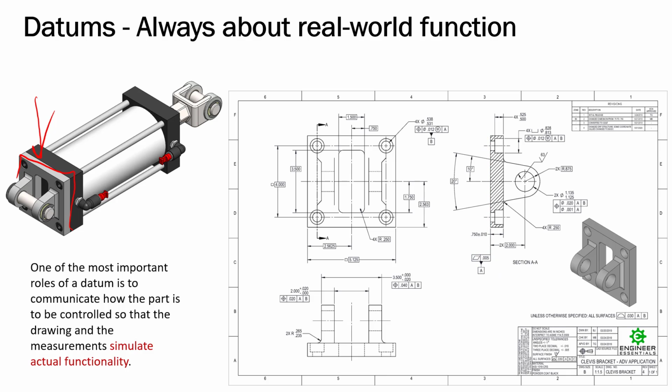The second thing that's going to happen whenever we assemble it is we're going to put in the 4 bolts. So we're not doing alignment around the exterior of this. We're placing the 4 bolts in there, and that's going to not only locate it, but it's going to stop the rotation. So it's going to orient this part to the assembly as well. So that's why datum feature B is up here on the 4 bolt holes.